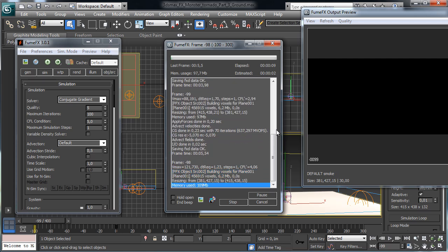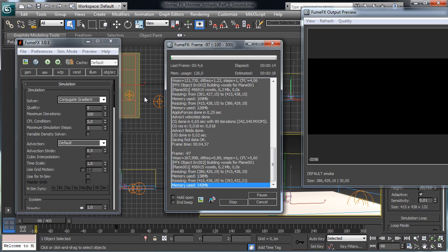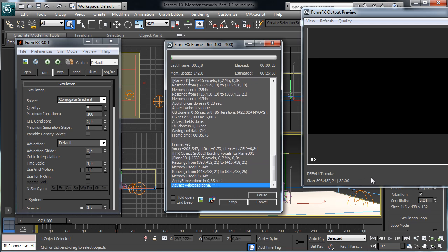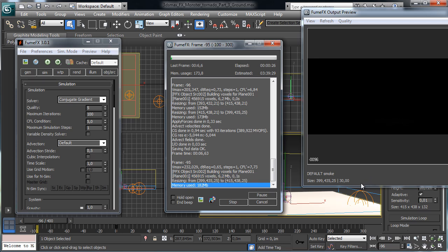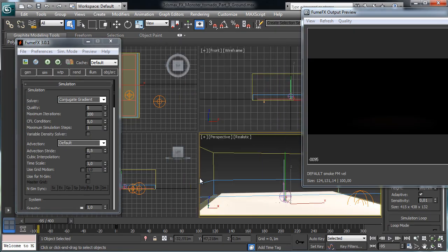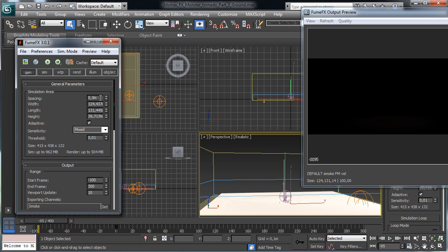and we can use this one and play a little bit with the rendering parameters to have a less dense value, because I'd like just to have a little bit of dust moving from the ground. So let's wait for some frames, because we have to see how it looks. Maybe we can just speed up using 0.5, and then the final simulation can be done using 0.3.